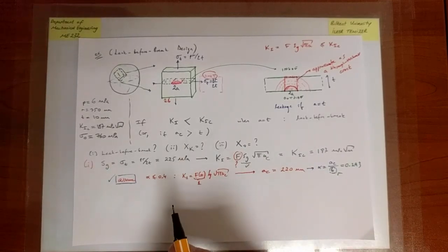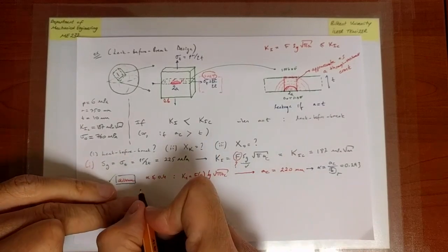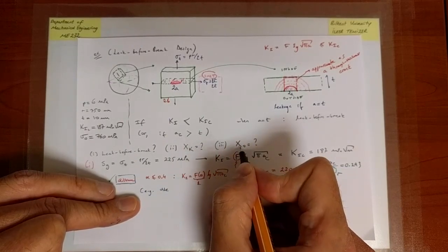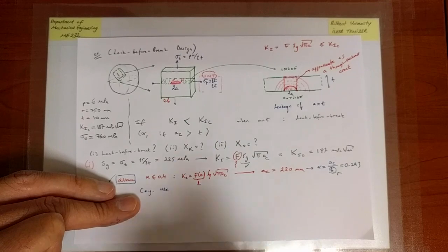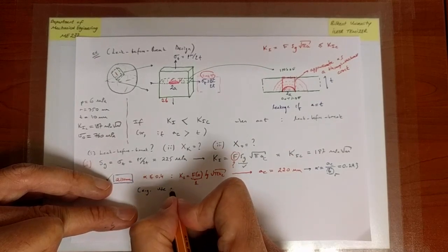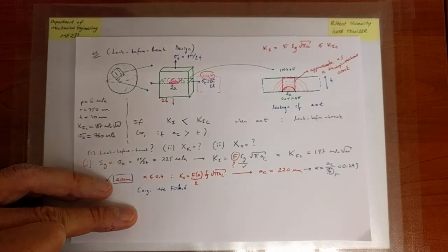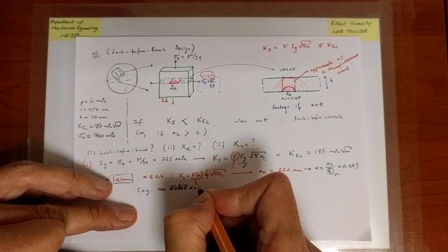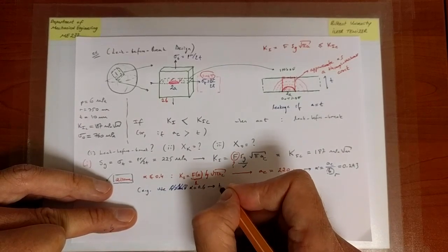Now, if you're not happy, you can experiment with this expression and, as an example, use a much harsher value for F, because if F increases, the critical value of AC will decrease. If it decreases, perhaps it comes very close to T or even goes below it. Here we are using 1 because I'm using the 10% limit. Why don't we just go ahead and assume F is 1.6, okay? So that's a rather large value. In fact, let me correct this. I am sorry. I'm going to use alpha equals not less than 0.4, but I'm going to assume that it is 0.6. And when alpha is 0.6, F comes out to be 2.